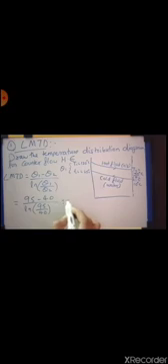Substituting the values, that is 95 minus 40 divided by ln of 95 divided by 40, we get 63.58 degrees. That is LMTD is equal to 63.58 degrees centigrade. This is the first part of the question.